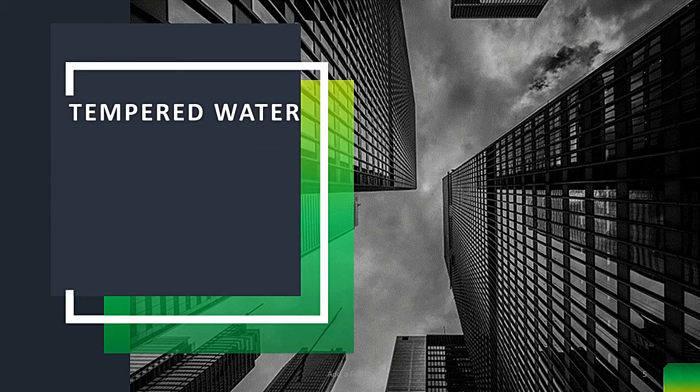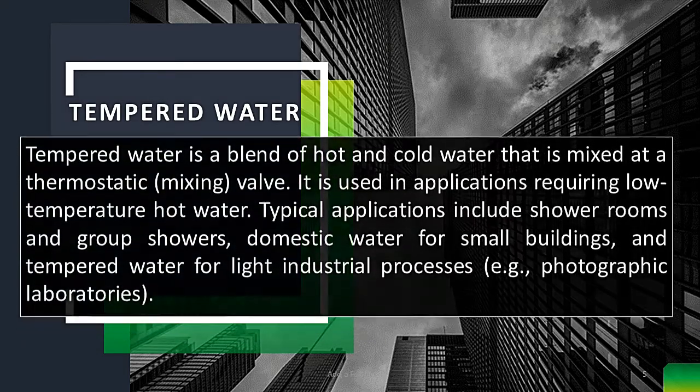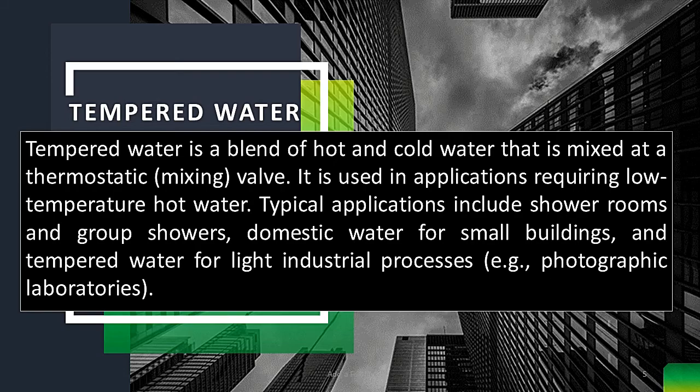Next one is the tempered water. Tempered water is a blend of hot and cold water that is mixed at a thermostatic mixing valve. A thermostatic mixing valve is a valve that blends hot water with cold water to ensure constant safe shower and bath outlet temperatures, preventing scalding.